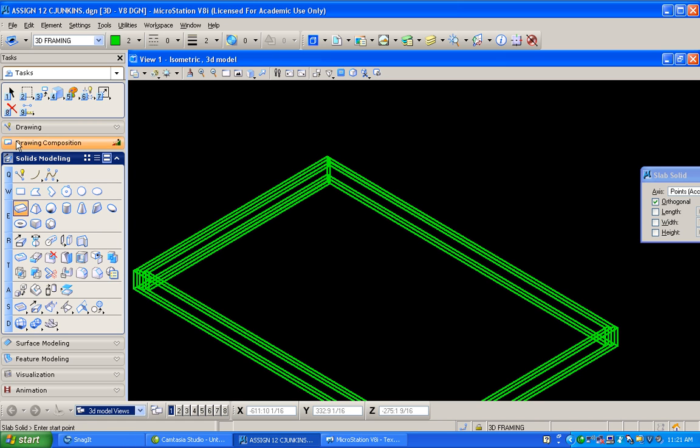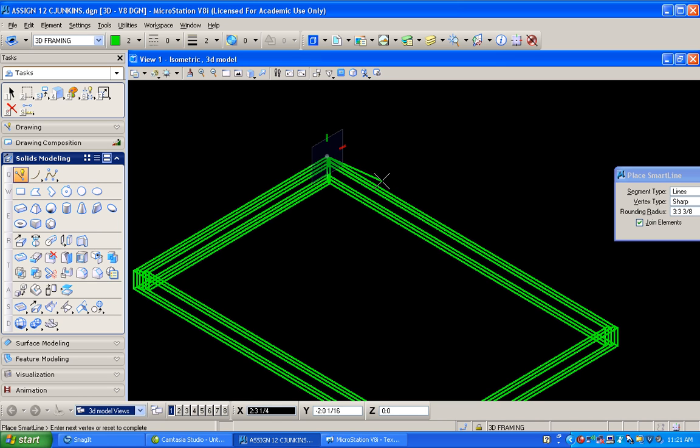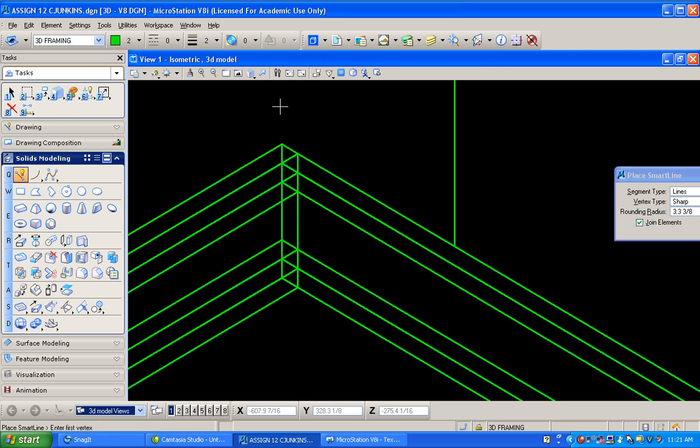So I want to set a point, a line here, from the outside corner edge, and hit S for side. I want to go down. I'll just left and right mouse button on this outside and hit O, and go down colon 16 and just draw a vertical line. That's where the center point of my first stringer needs to go.